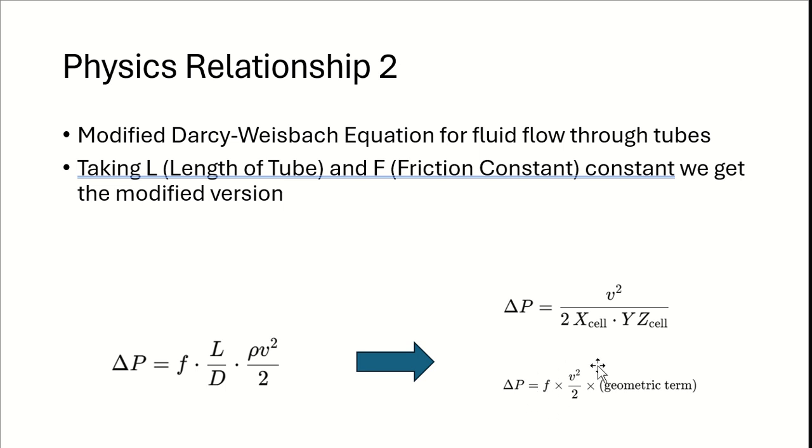Obviously, I'm keeping the Fanning friction coefficient constant here, but I want to drive this relationship home a little bit in the model. And it's important to me that I don't weight this as high, because the data obviously has its own friction coefficient and its own L. However, if I can enforce the relationship where V squared, or the average velocity, scales quadratically with the pressure drop, I'm able to give the model a little bit of support at these collocation points, where it can try and at least see the relationship in the collocation data.